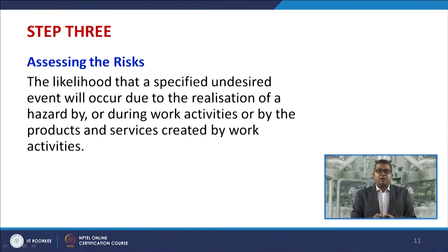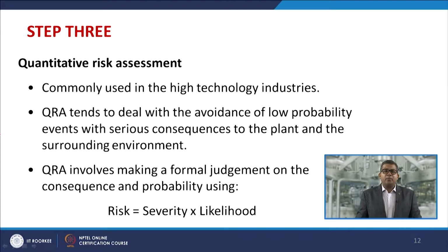Risk is the likelihood that a specified undesired event will occur due to the realization of a hazard by or during work activities, or by the products or services created by the work activities. This is the assessing of the risk. Now, let us have a look at quantitative risk assessment. These are commonly used in high technology industries. Quantitative risk assessment tends to deal with the avoidance of low probability events with serious consequences to the plant and the surrounding environment. So, that is why they are very important.